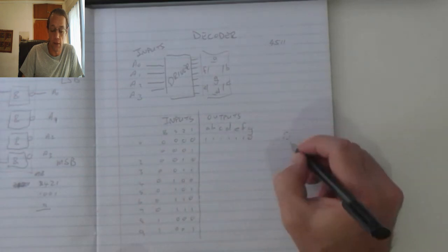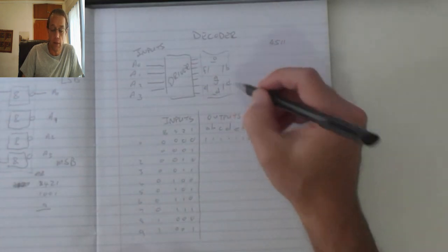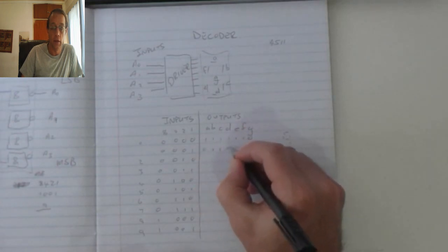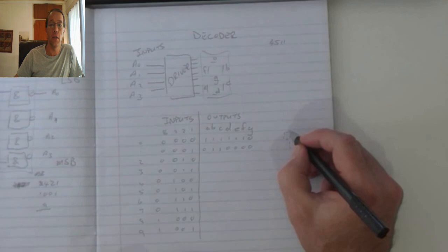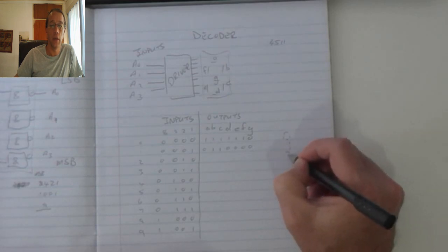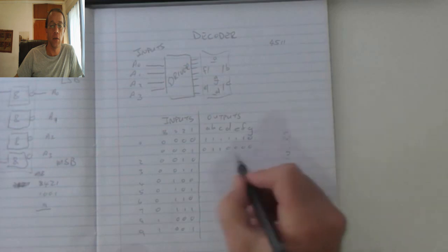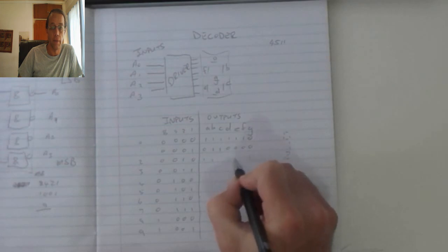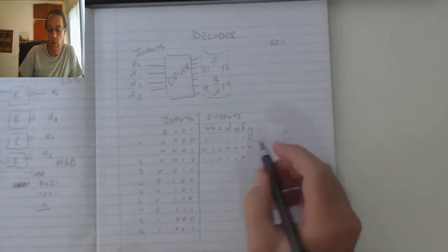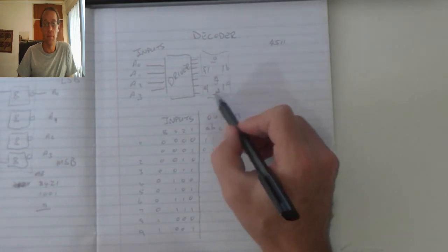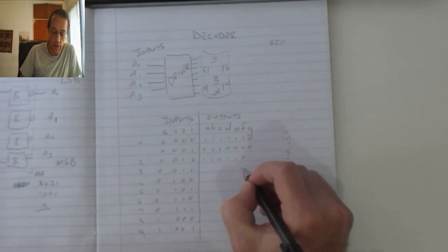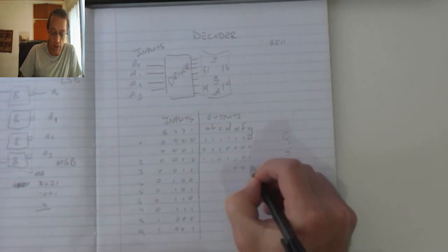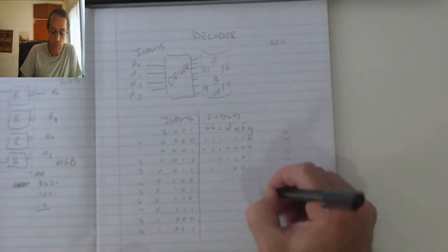So my 1 is going to be represented by those two, which is B and C, and the rest are all zeros. 2 is top, down, horizontal, down, right. So that'll be A, B, G, E and D, with C and F 0. 3, they are all going to be on except for F and E. And the process continues down to the bottom.